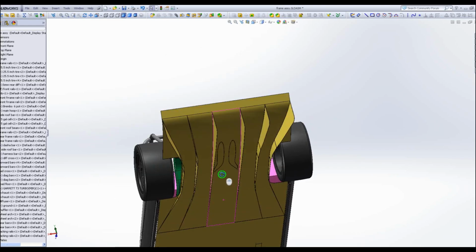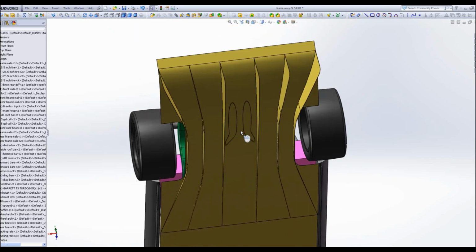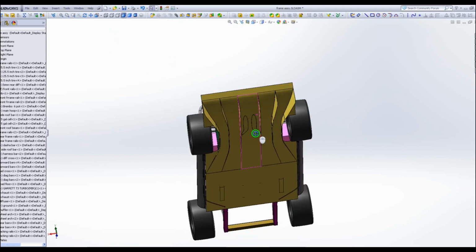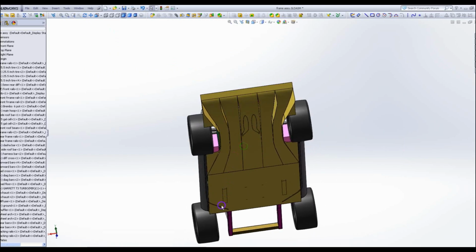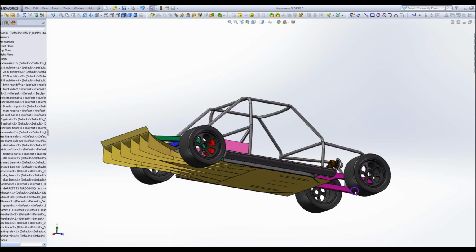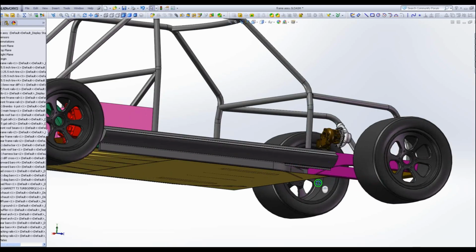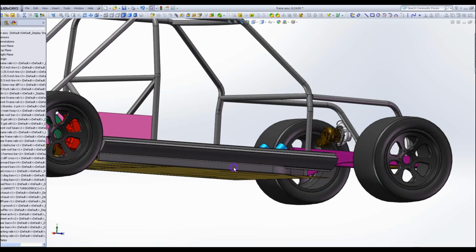And I'm gonna have to play with these areas. I'll make a little spreadsheet up to figure out what the area ratios are here. This is a starting point, but definitely not done. I have to do some math on it, but this is in general what it's going to look like. I got some jacking rails on here. This is to let the air out of the front in that area. I'll probably get rid of this pinch weld too, so the air will come through and go around there and out.